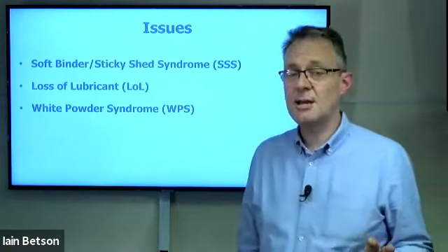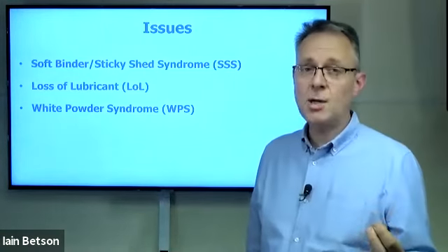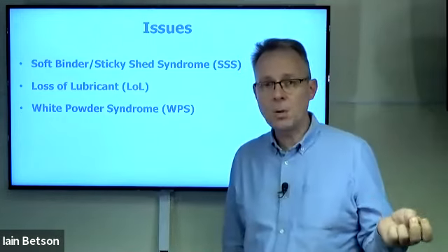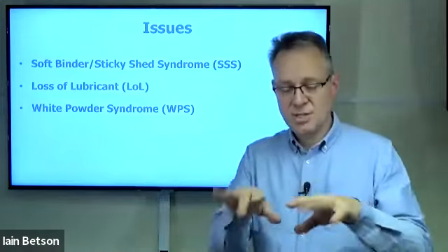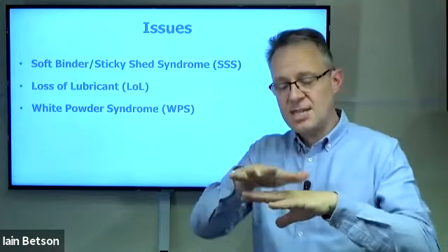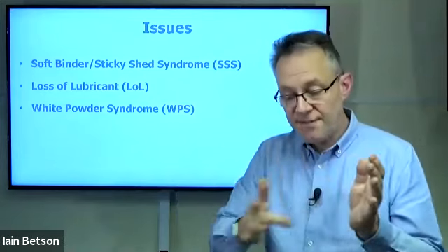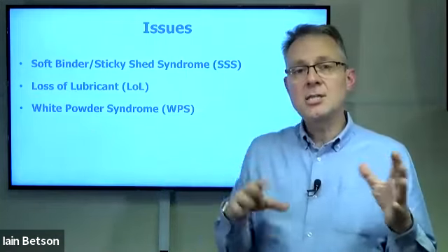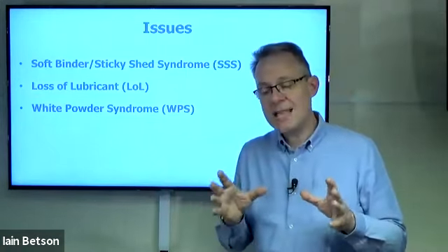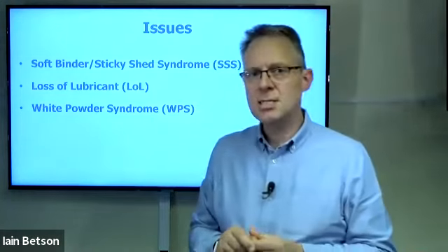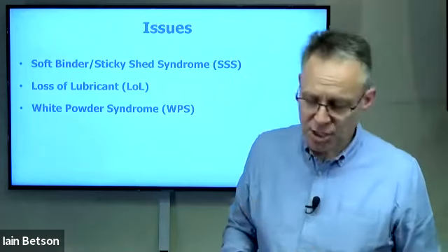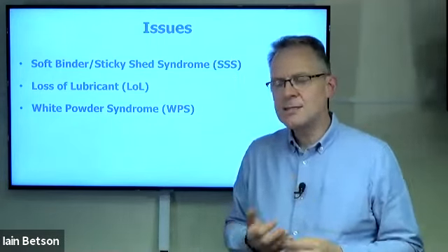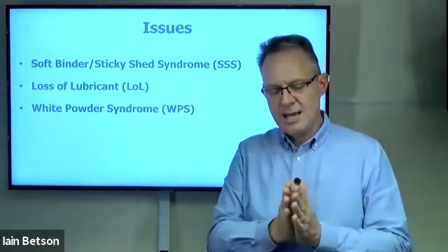You can get some tapes that do have a lubricated tape. Indeed, ATR make one. If you're into your music recording and have heard of a 1970s device called a Space Echo, it uses graphite lubricated tape, because it's not on reels. It actually sits in a kind of box where the tape is fed through a replay head and a record head, pinch roller, and then back into the storage box again to stop that tape snagging. It is actually lubricated, and they make a lubricated tape for it again. But by definition, most tapes didn't have lubrication on them. Yes, the backing acted as a way of smoothing the path, so to speak, but it wasn't actually lubricant.